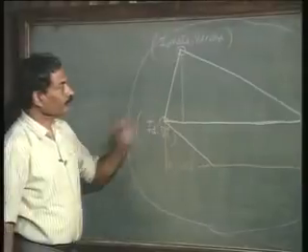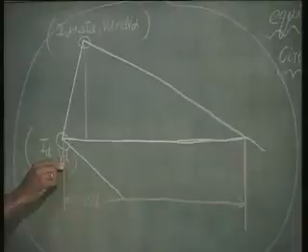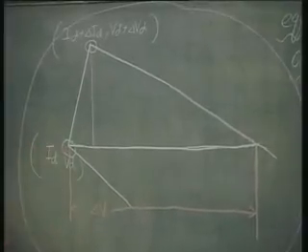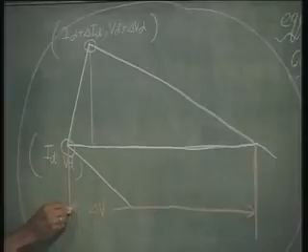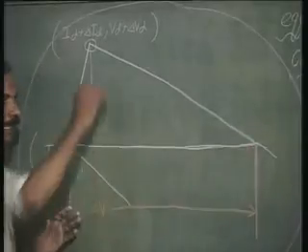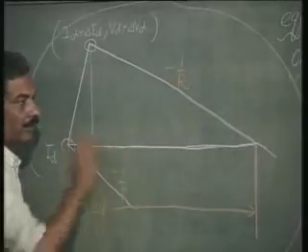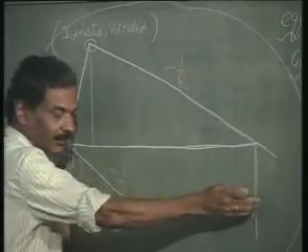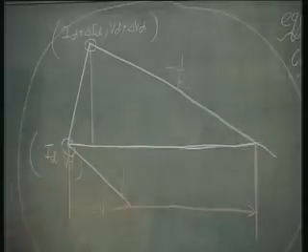So, we were originally at an operating point which is I diode, V diode, and we shifted because of a change in voltage from V to V plus delta V. So, delta V is the change in the x axis, from here to this point. These are two parallel lines with slope equal to minus 1 over R. This is the slope. So, the intercept here changes by delta V. So, this base is changing by delta V. The slope here is minus 1 over R and minus 1 over R.